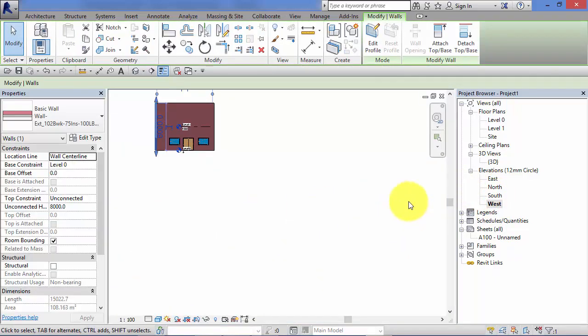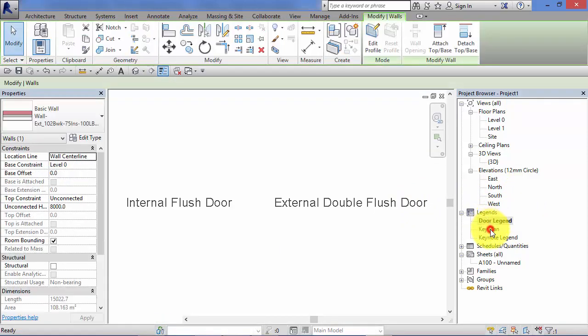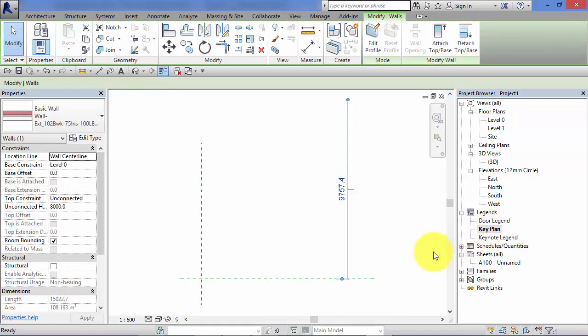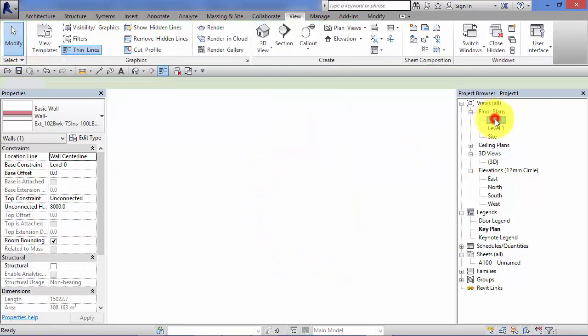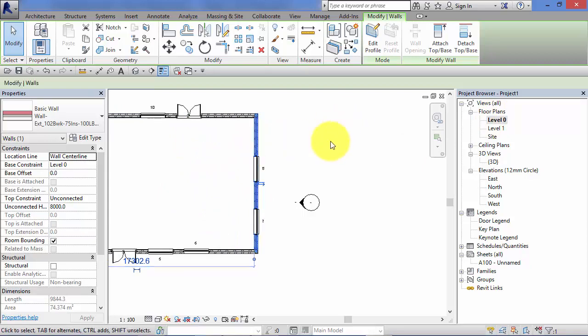So if we maximize a window and we carry on opening views, all those views that we've opened previously are still there in the background, and we've just seen how if we make a change in one view, it gets updated in all the others. That is still the case when you have a window maximized, as we do here. All those other views are still being updated.